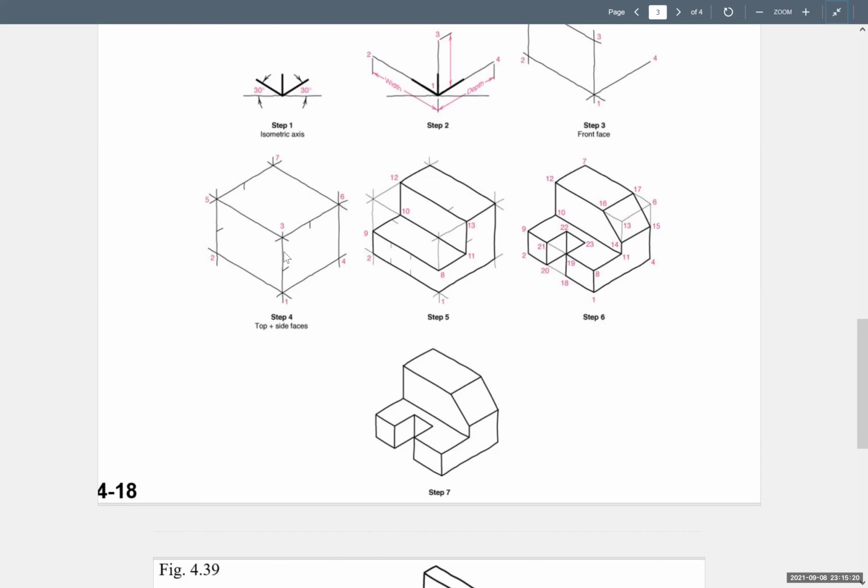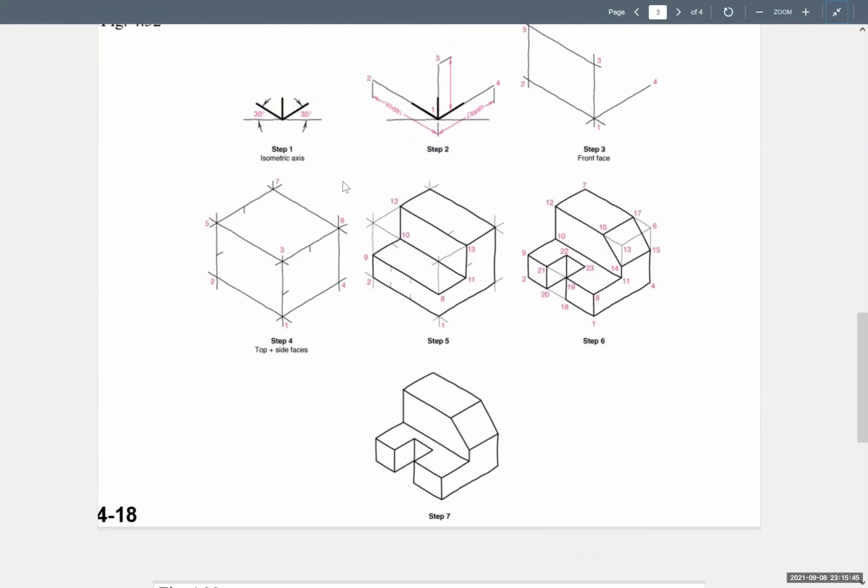And then from the front, I could have done it here. I see that there's a piece cut off, and I could have measured the height here and the width here that it was cut off. I measure the height and the width, and I cut this corner off both in that back plane and in the front plane. So what's really happening is you draw your whole cube, and then you start drawing things in the front, and you're drawing things as you're going back in parallel planes.